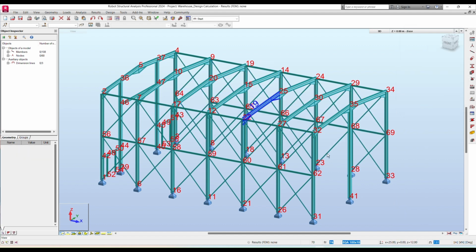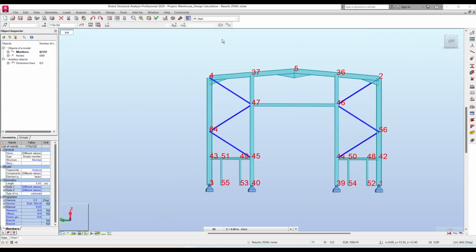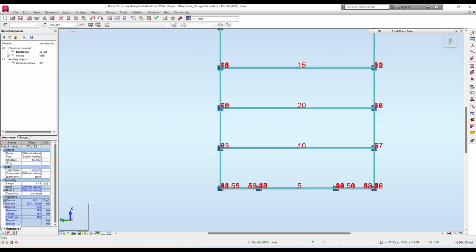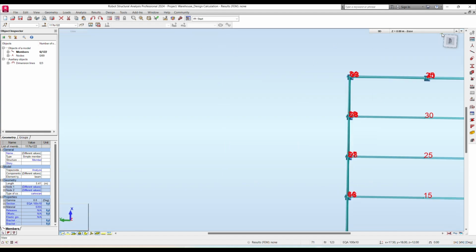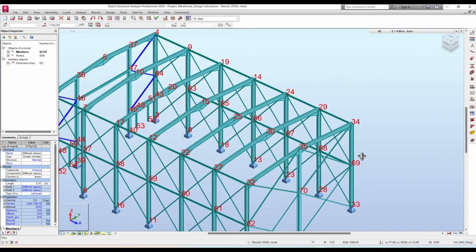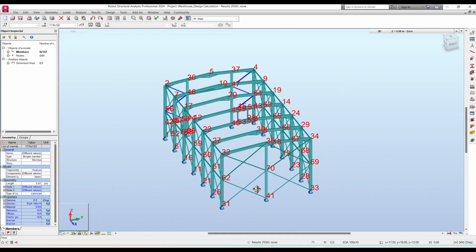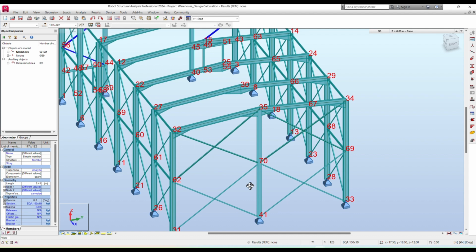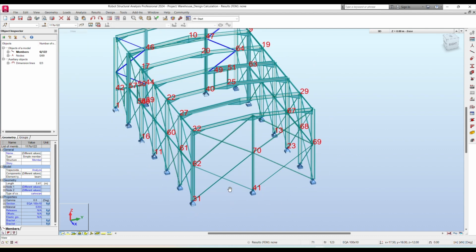Now we need to create the bracing in the shorter direction, using the same method. In the shorter direction we have created the bracing like this, N bracing, where the rolling shutter and door are coming. In the other direction, where there is a mid wind post, we are forming the X bracing.